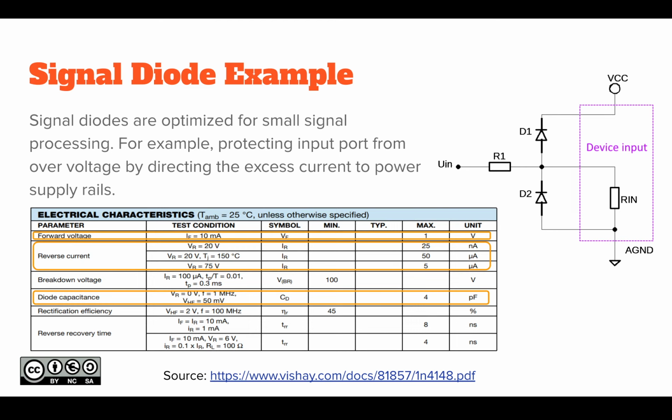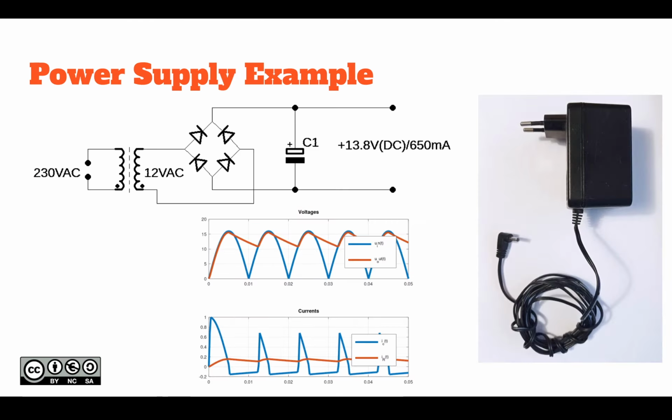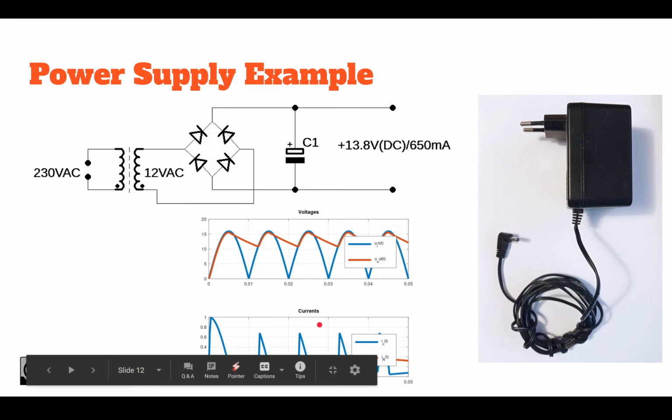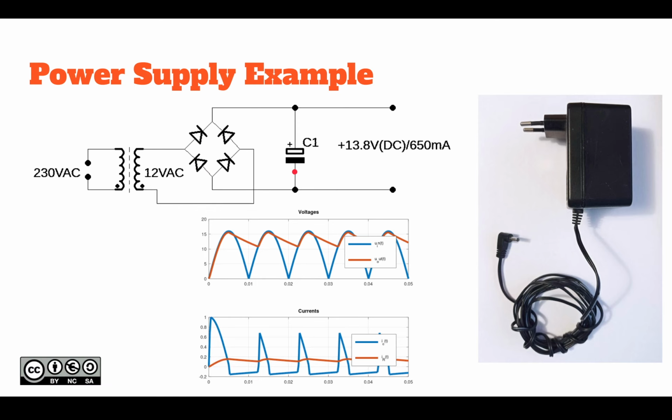All right. Another application for diodes, different diodes. Those were power diodes. So in here, the rectifier diodes actually have to be something like 1 amp diodes, because look at the currents of the IC when you start that system. So the maximum current for the capacitor is 1 amp. So all of these diodes must withstand that 1 amp current.